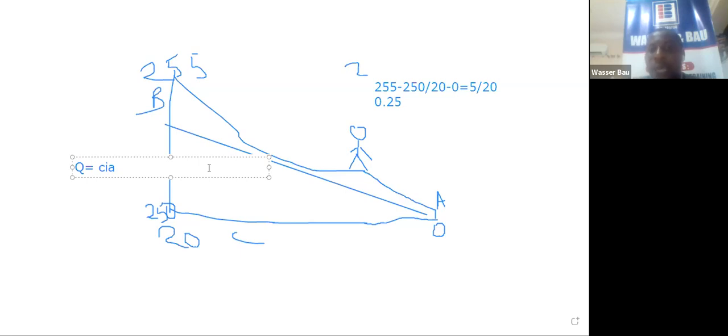But here in most parts of sub-Saharan Africa, depending on whether it is crossing a roadway, depending on the overburden, it should not be less than 0.6 and should not be more than 1.2 for economic reasons. In some cases it can be more than that, but you must consider the economics of laying the pipes. So between 0.6 and 1.2 is what we normally use here. I stand to be corrected. If you have another opinion, you can give me. But in some countries, the standard varies.